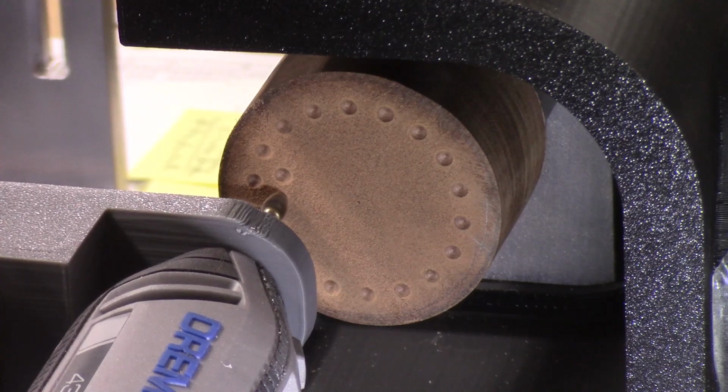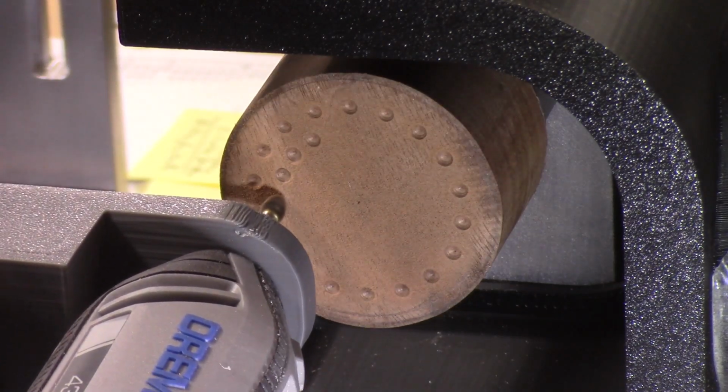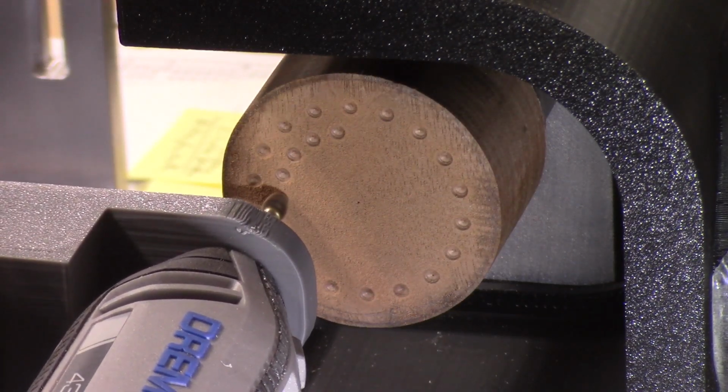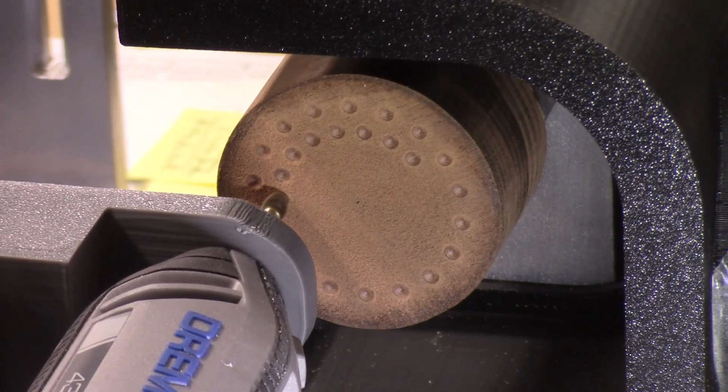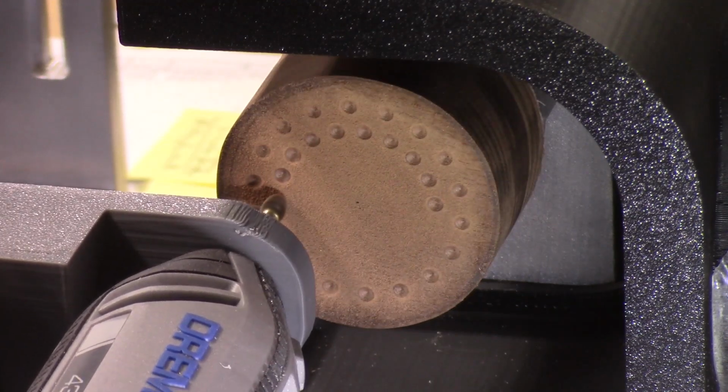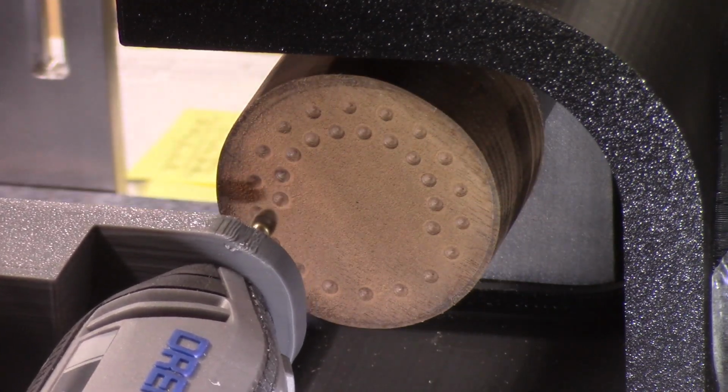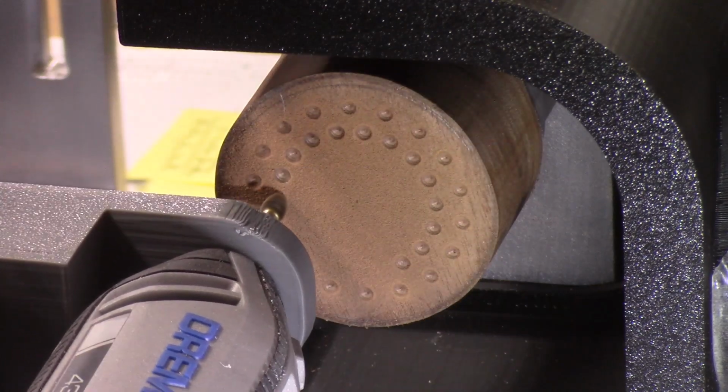Here I'm showing the cutting of the second pattern layer of indexed holes. For this layer I set the offset angle to stagger the holes between the holes in the previous layer. I also created a program to create index patterns on the side of a cylinder, but as yet I have not tested this program out.